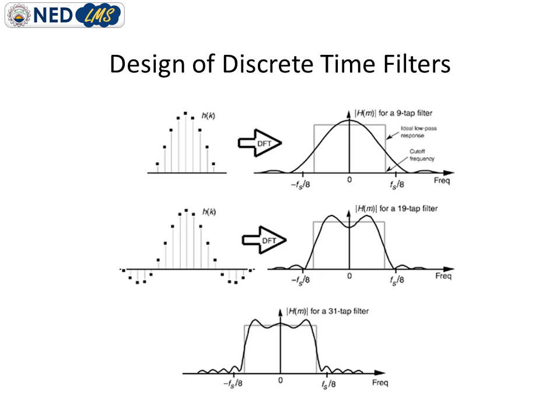And the response of that particular FIR filter can be analyzed by just taking the FFT of this impulse response, which you already saw in these three figures. As I increased the number of filter coefficients, my response becomes sharper. So this is basically the concept behind designing discrete time FIR filters.